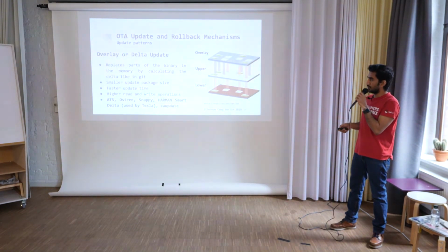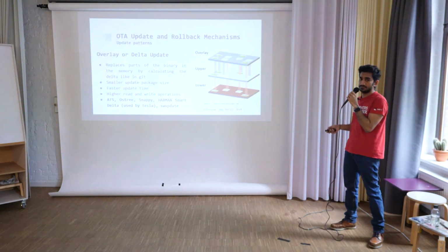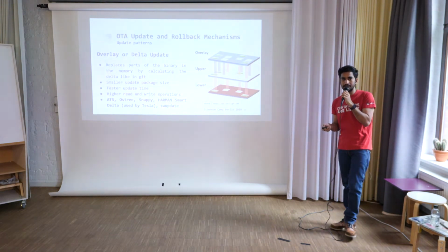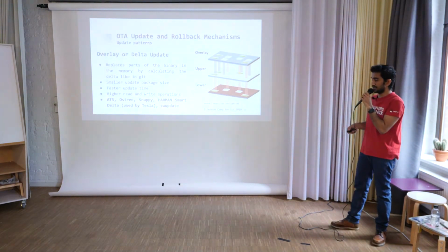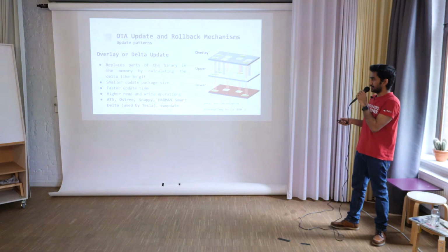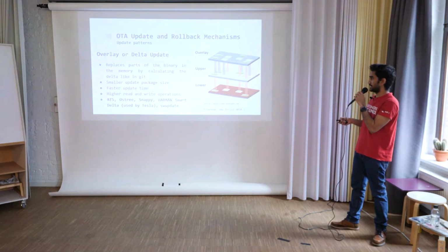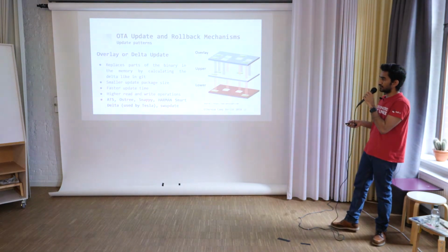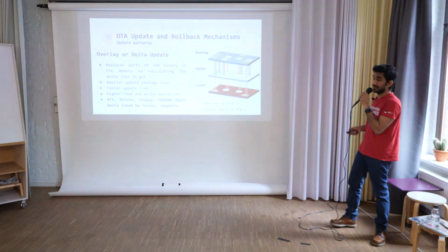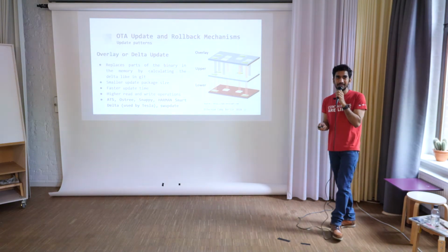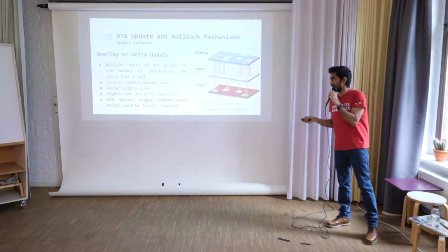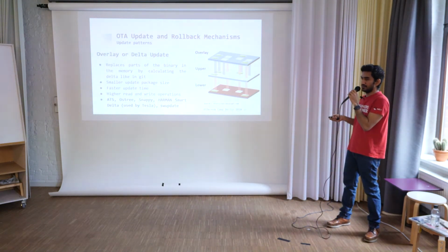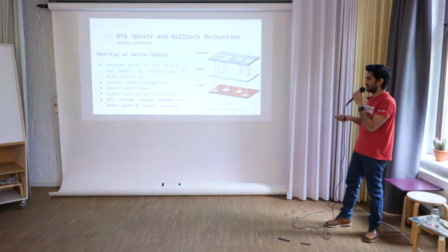So this is overlay or delta, which is basically like Git. It takes the differences and updates only that part, with a smaller package size and faster time. The problem here is that it has to do a lot of operations on the root file system. For example, if you are making a product for industry that has to stay for 10 years, this is going to kill your memory, whatever the flash is.